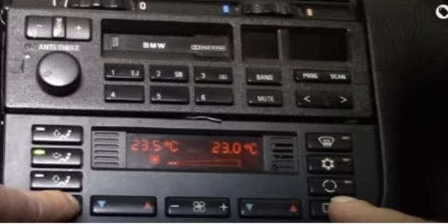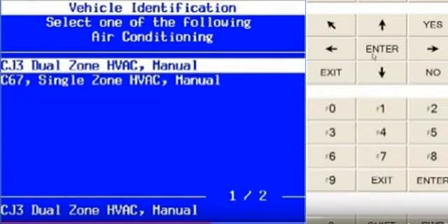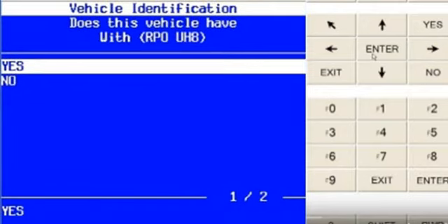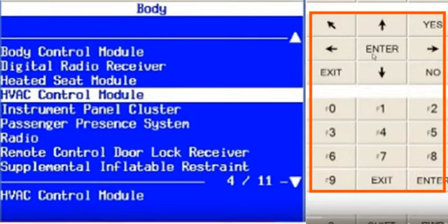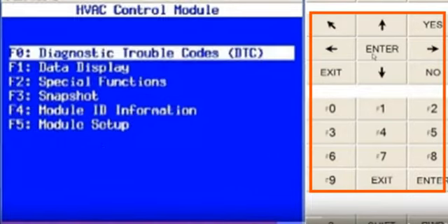Some control heads for automatic climate control will have built-in diagnostics. This consists of holding specific buttons on the control head for a specified amount of time. This will let the technician enter the diagnostic mode and manually control the system as well as retrieve any faults. Not all vehicles have this option. The second method is to connect the scan tool and manually go into the AC system and prompt commands to the various actuators. Now enter the simulation to learn more about multi-speed blower circuit operation.